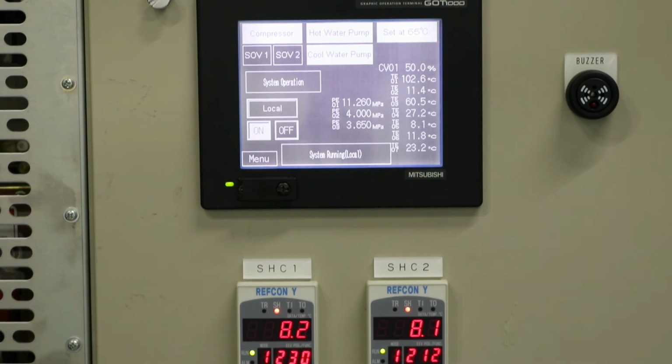As you already know, the evaporated CO2 in the evaporator goes right back to the compressor. We must prevent the event in which not all CO2 is evaporated, such that some of the CO2 stays in liquid form, because the compressor will be destroyed when the liquid gets into it and it gets compressed.